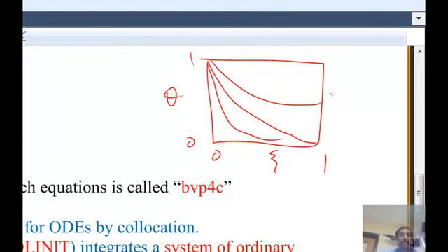Okay? So the first thing I do is go into MATLAB and search. You can search help boundary value problem. It'll point to this particular function, BVP4C. That is the name of the function. You are adding to your knowledge of the various functions. So far we have seen backslash operator, fsolve, fminsearch, ODE45. This is probably the last one that we will see in MATLAB, BVP4C.